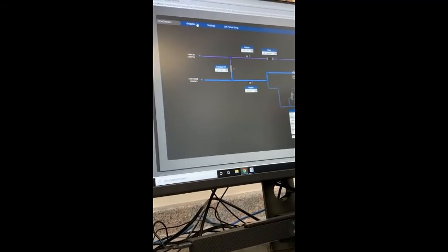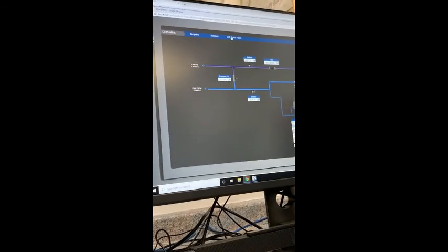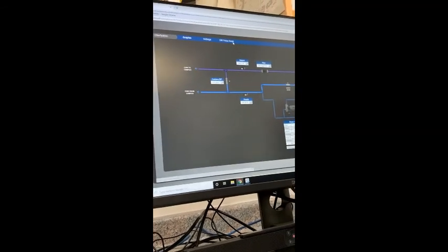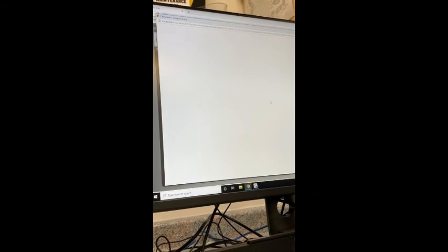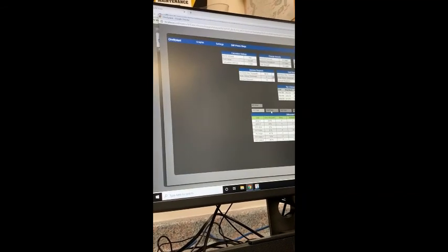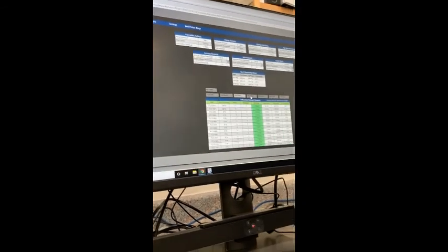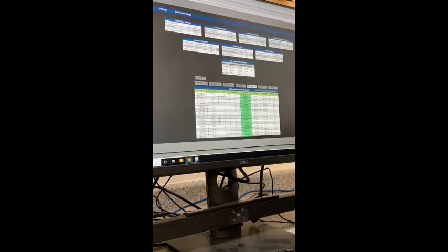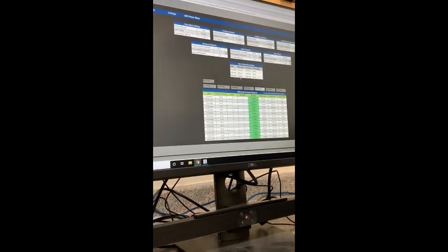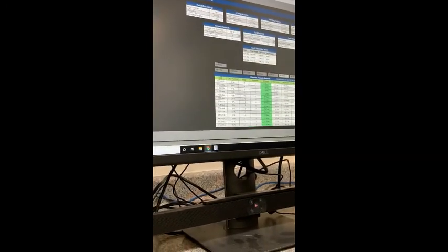So this is the graphic view, the settings, and then the differential pressure requests, where you can go in and see which one is requesting, all the different units, which one. Fan coils. Yeah. So from here, you can select the different floors and see which ones have been the worst ones out of all of them, what their units are, how many hours, etc.